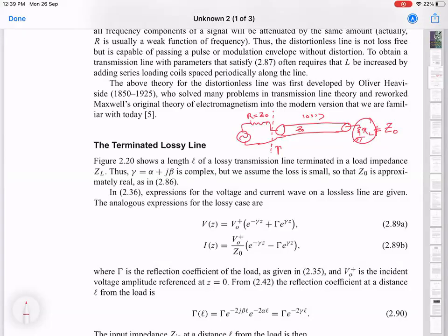What this is telling you is that if you use a one-port setup like this one, so you have a source and it sends some signal, reflects from the device and comes back, you will not learn anything about the actual device if the intervening transmission line is highly lossy. Again, it seems like an odd scenario, but in most cases, when you look at only reflection measurements, you just connect your device directly to this instrument called a vector network analyzer, which will send out a signal and measure what comes back.